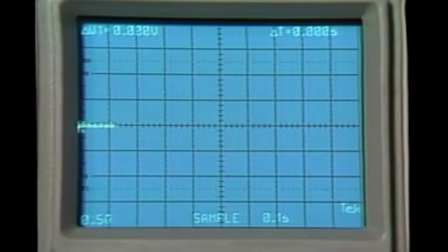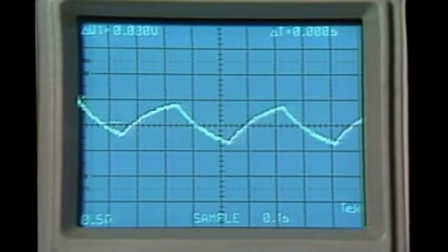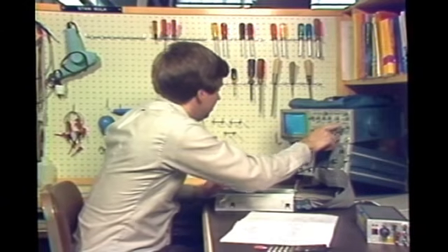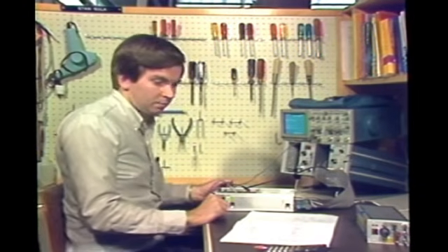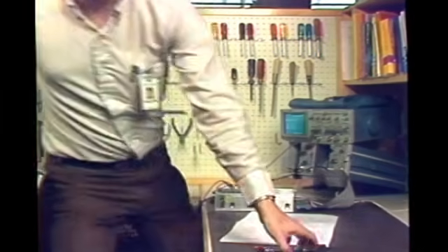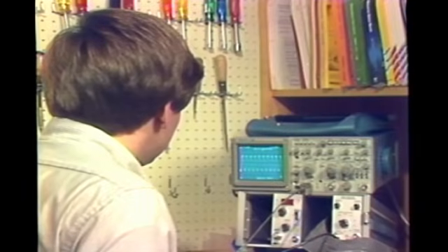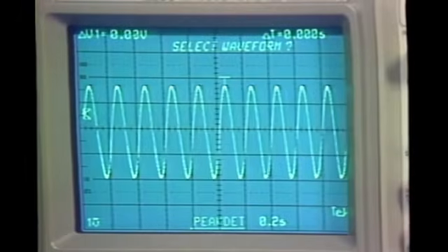Scan-roll-scan is a single sweep mode. The scope scans from left to right to the selected pre-trigger point. Then the display rolls right to left. When a trigger occurs, the scope scans the rest of the waveform to fill in the record. Freezing pre-trigger information as well as the waveform allows you to see what caused the scope to trigger. This feature is especially useful for babysitting. You can set up the scope controls to capture a rare event, then do other things while the scope waits for the proper trigger event. When you return, the scope has captured the event plus the pre-trigger information.